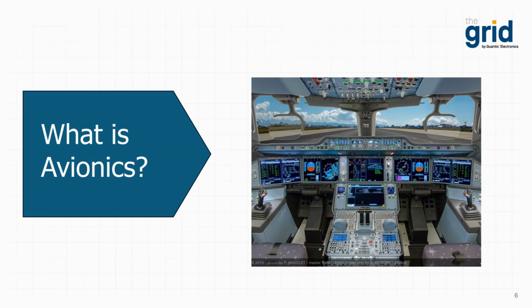While avionics systems are found throughout an aircraft, the cockpit is where a majority of these integrated avionics systems are housed. These systems are crucial for flight operation, navigation, communication, and overall aircraft management. Key systems located in the cockpit include the flight management system, which is a computer that manages flight planning, navigation, performance calculations, and data logging. Now, this actually interacts heavily with other systems. Other systems include autopilot, traffic collision avoidance systems, ground proximity warning systems, radio communication, navigation systems, flight data recorders, weather radar, and much more.